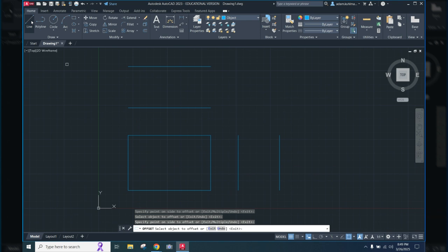All right, now I'm going to grab the line tool and using my snaps, I'm going to fill in the ends. And I kind of overshot that one. I'll come back and trim it. So I'm going to hit spacebar again, and I'm going to get it to snap to those endpoints. Spacebar will free me from the line tool. Spacebar will bring it back up.